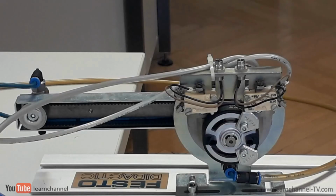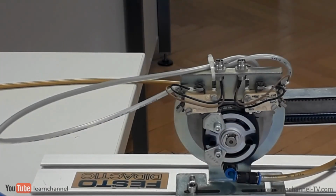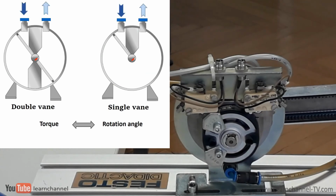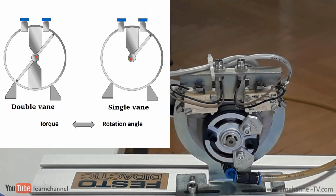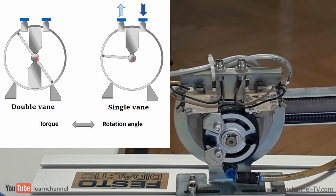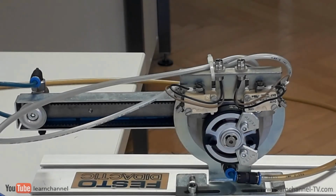Vane cylinders have a cylindrical chamber in which a vane is mounted to a central shaft. Air pressure on one side forces the vane to rotate until the end of the stroke is reached. You get vane actuators in two designs. The single vane design has a relatively large rotary motion, up to 280 degrees typically. The double vane type offers a less rotational range, which is limited by half but produces twice the torque.